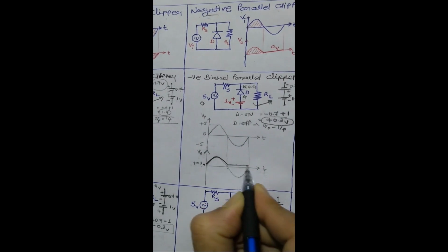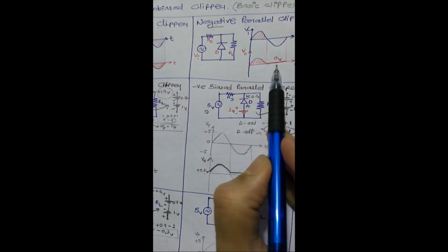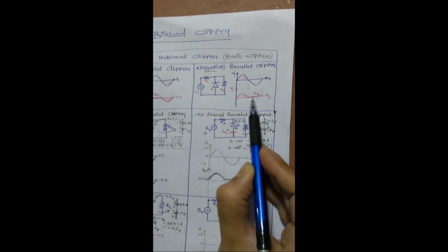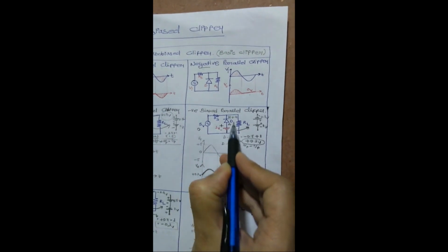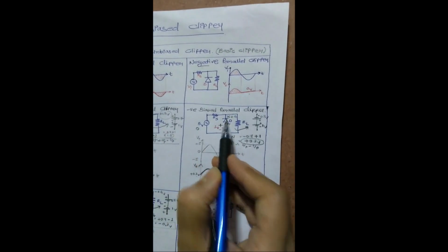So in this case, initially without bias, your negative level is 0. When the upper plate is positive, your voltage is shifted to the upper side. This is a trick. And this voltage is defined by some simple calculation of these two biases. Diode is one kind of 0.7 bias and this is a 1 volt bias. Consider the next case: the minus plate is on the upper side, the lower plate is plus. Consider input is equal to 0. Then think about the first case, D on, D off.